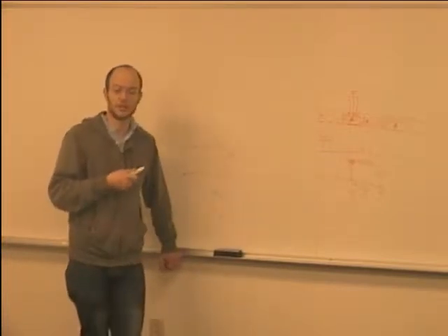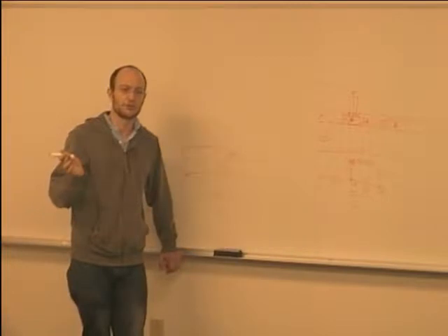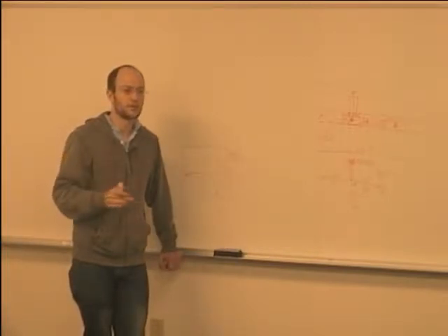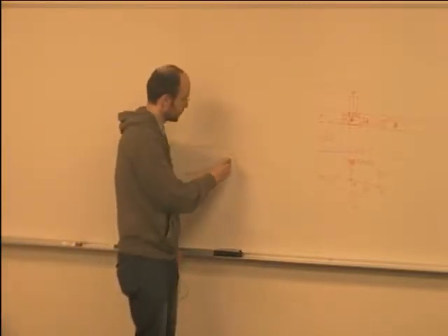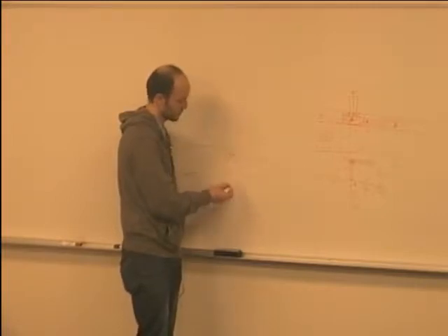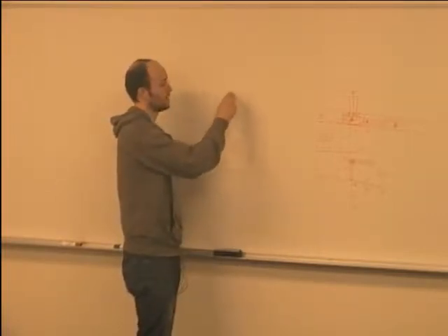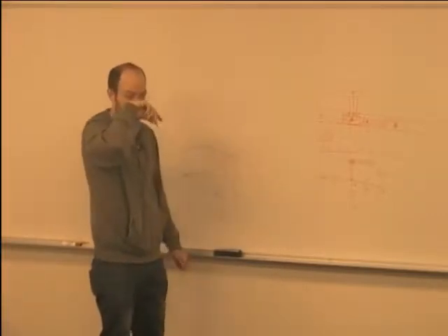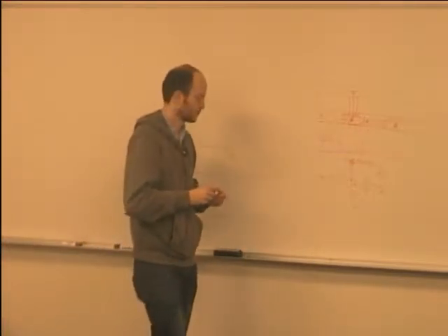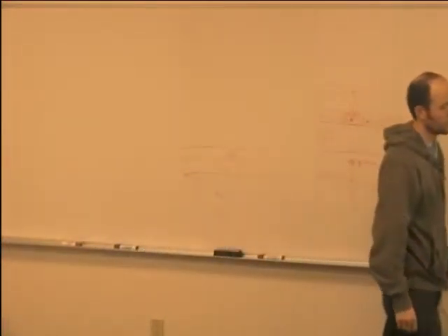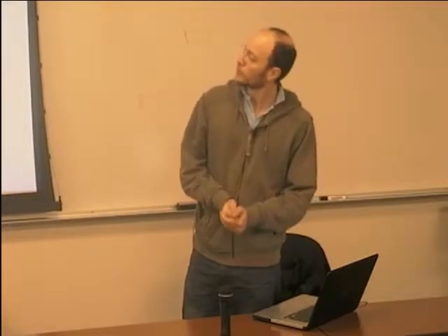So per unit area, it has more capacitance. Does this make sense to everyone? And if you take metal 1, if you take metal 3, it will be even farther away. So if nothing else, you wouldn't want to use diffusion because of the capacitance.